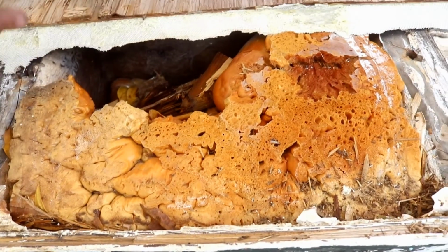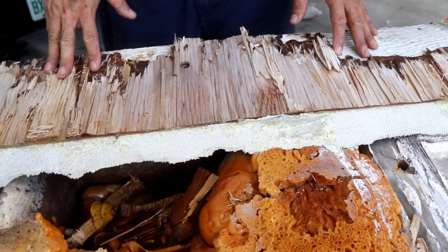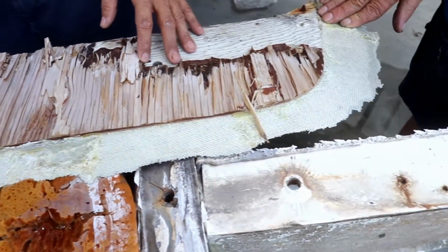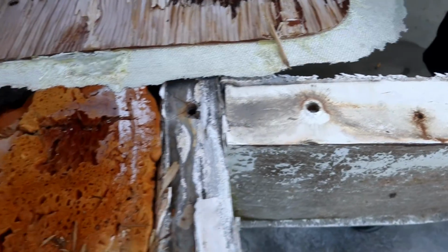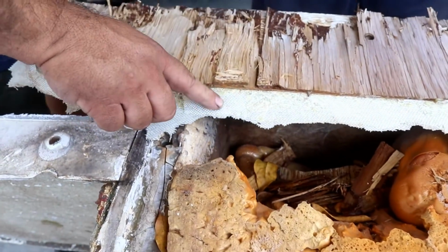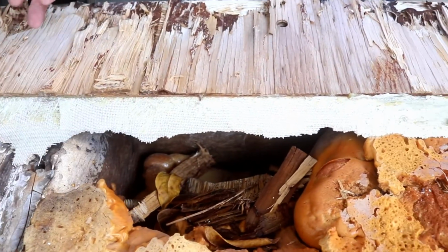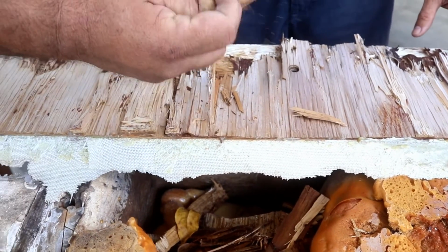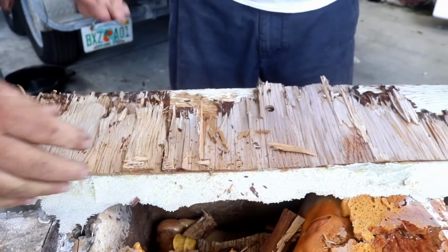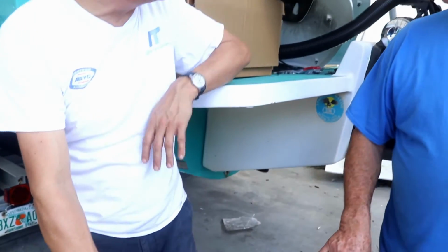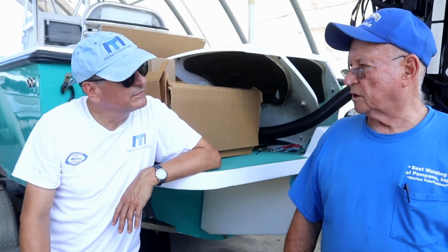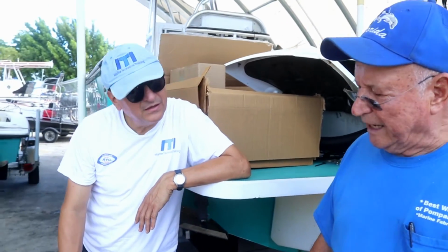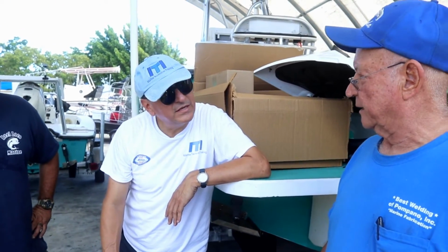And Kiki will explain to you, like you know how Kiki made that other platform that was closed in? They made it with wood, and the material inside never got fiberglass. And it's polyester resin. That's not good. And you see what happens to the wood? It absorbs humidity. This foam is not good, no? No, sir. That's the worst thing you can do.